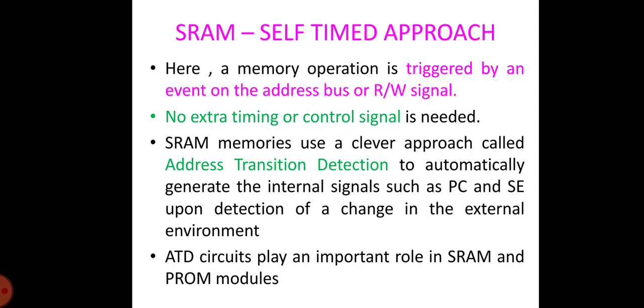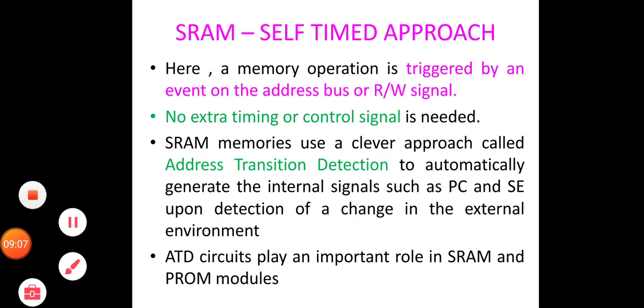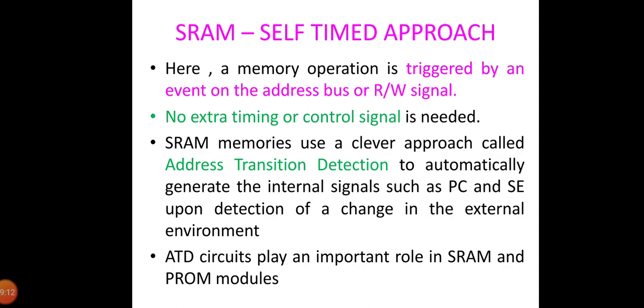For instance, the DRAM cell capacitance has degraded from approximately 70 picofarad for the 16 kilobit memory to below 30 picofarad for the current generation. Simultaneously, the voltage levels have decreased for both power consumption and reliability purposes.